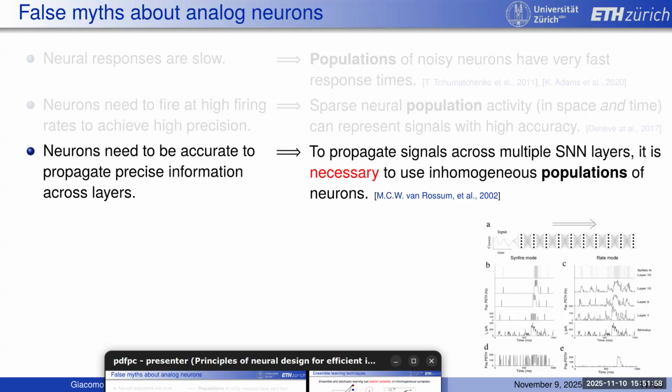So the way that the signal is encoded, if you have some analog waveform like a biosignal, it's possible to use an adaptive neuron to do a sigma delta type where you look for changes, or if you just send directly the current into the neuron, you do pulse frequency modulation. So the rate of spikes increases if the amplitude of your signal increases. So that would be pulse frequency modulation.